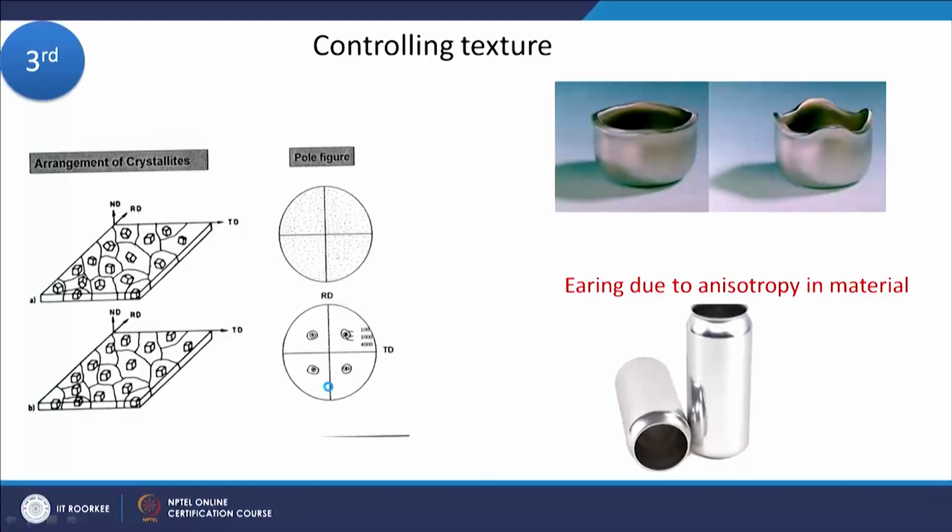So, if I do processing at lower temperature and higher strain rates, I will be able to get a finer grain microstructure. Of course, there are other effects we have to consider, such as whether we are introducing any defects in the material. It makes no sense just to refine the microstructure if there are defects in the material, because the defects will bring down both the strength and ductility.